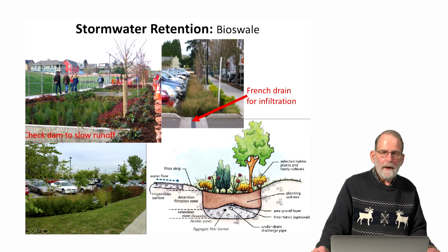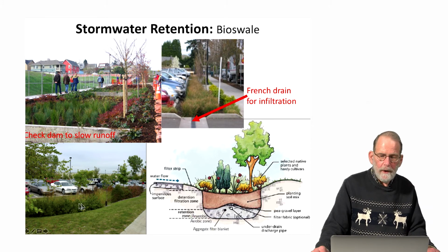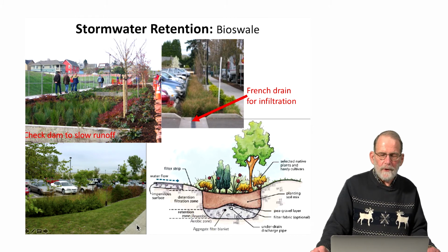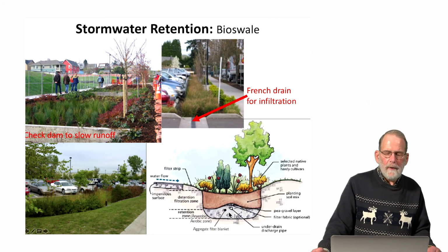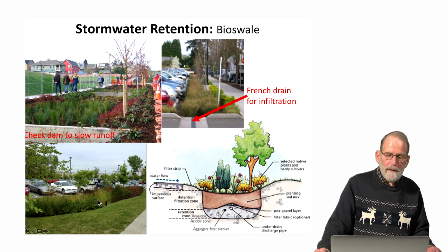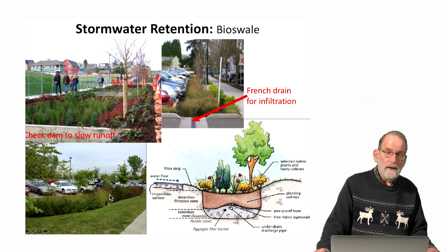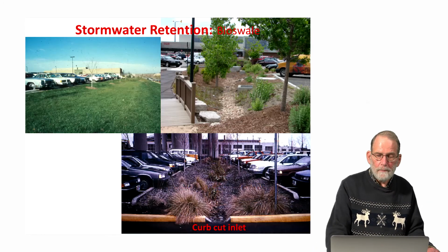In the lower left-hand diagram, we see adjacent to a parking area, a swale area that's been planted with various types of vegetation, so water sheets off of the adjacent roadway and the parking lot into the bioswale, infiltrates into the bioswale, into the lower gravel structure, and the evapotranspiration of the moisture back into the atmosphere again helps to reduce the volume of runoff. Reducing volume of runoff is absolutely critical.